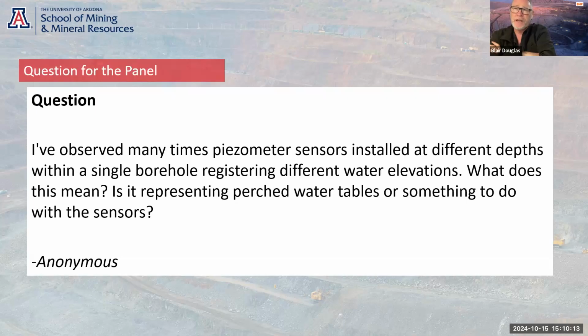Obviously, if you've got hydrostatic conditions, they'll all sit along the line of best fit. If they sit below the line, you've got downward gradients. If the probes are sitting on the upside of the line, it's typically showing vertically upward gradients and pressure conditions. So there are different ways to look at the monitoring data to get a sense of whether it is actually representative, and how you may want to then correlate it back to what Gus was talking about with geological units.